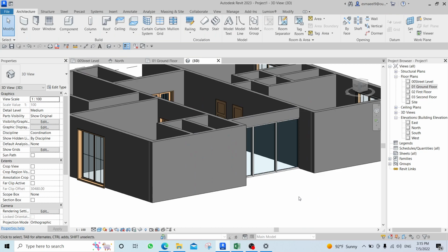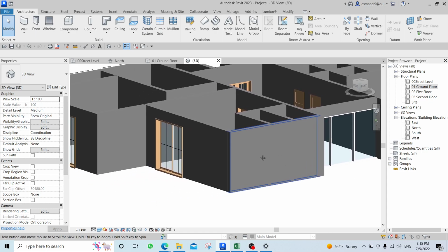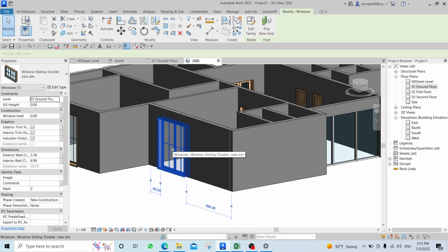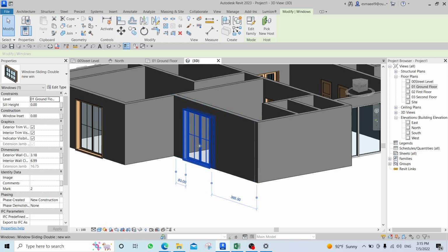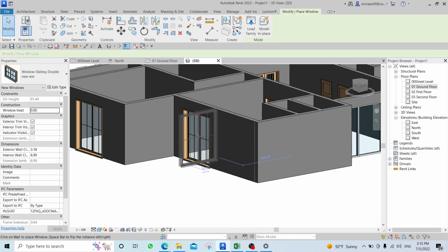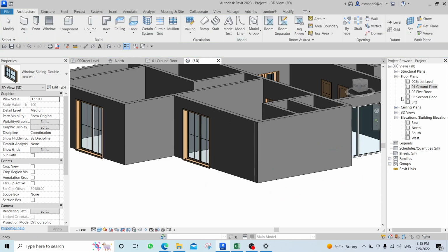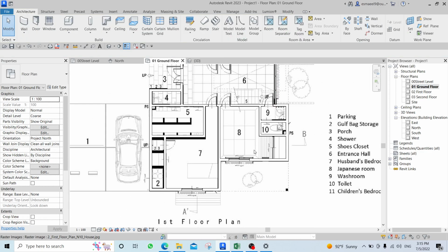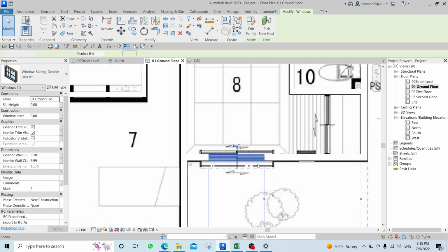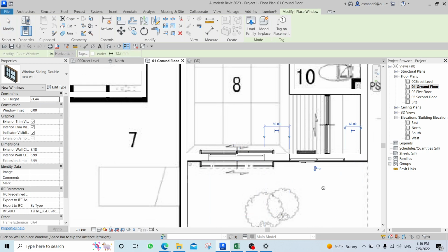Doctor? Yes. Didn't we use create similar to put the doors? Why did they appear different, like appear higher? Exactly. You mean with the windows? Yes, exactly. This is, I think, with the window. Look, now I'm creating. I will create similar for this window, CS. If I go to my ground floor, I will go to this window, CS. Click. Go to 3D.